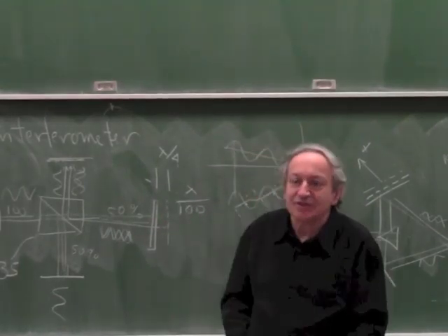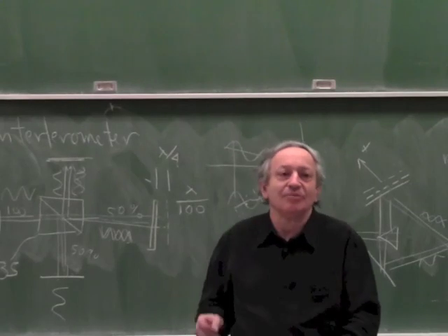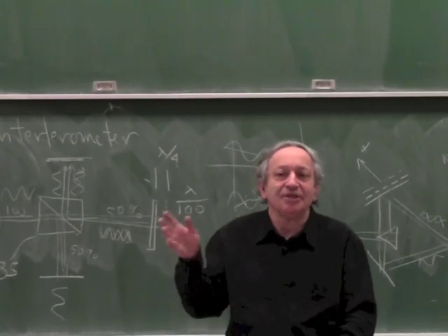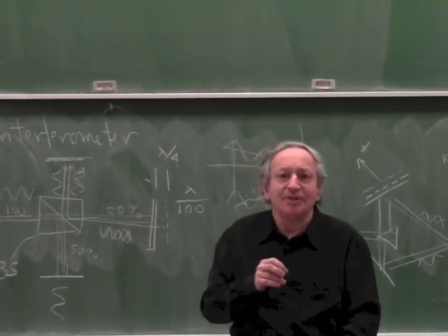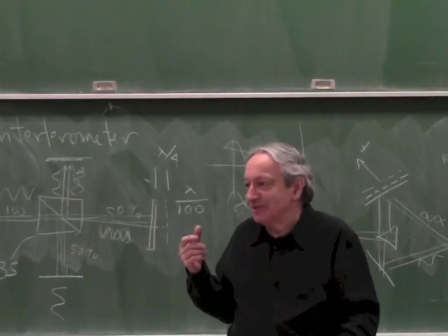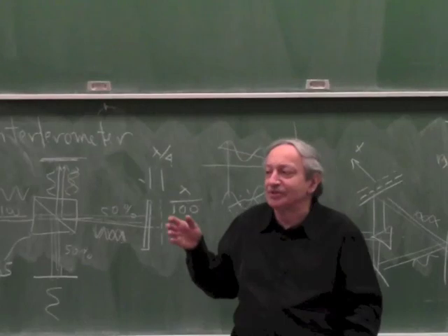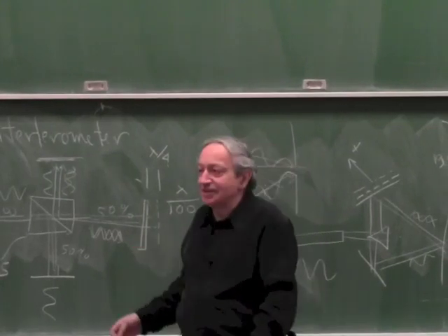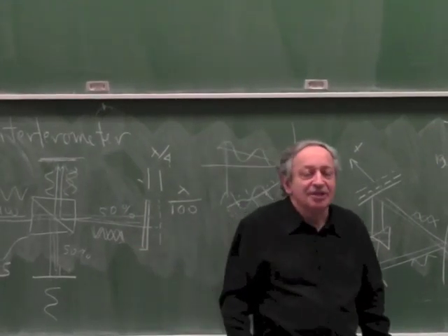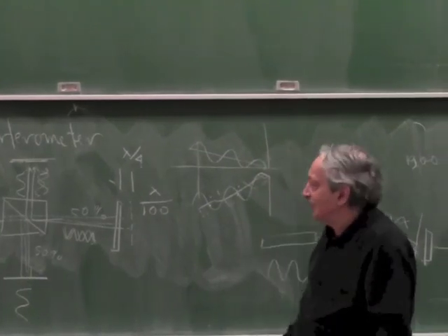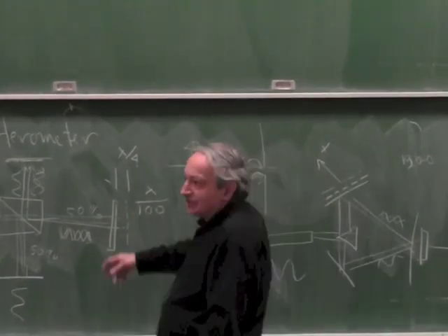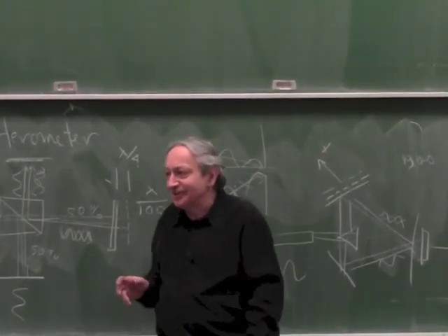But it's a very good instrument to measure from, say, 1 millimeter to 1 meter, because below 1 millimeter there are simpler ways to do it, like a capacitive sensor or an optical sensor. But between 1 millimeter and 1 meter or several meters, that's really one of the best instruments. It's expensive. Typically, an interferometer, unless you build it yourself, costs many, many thousands.